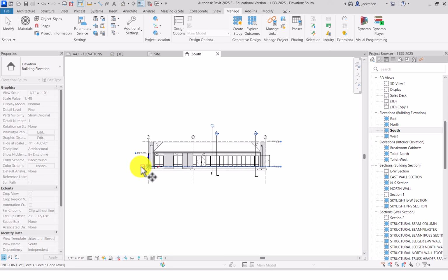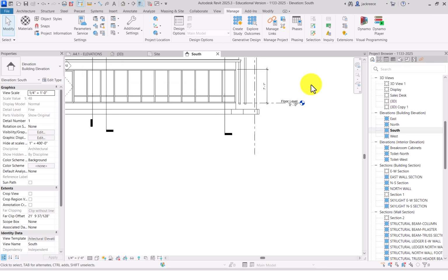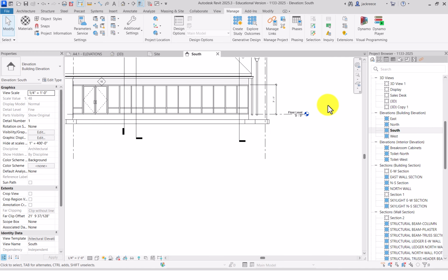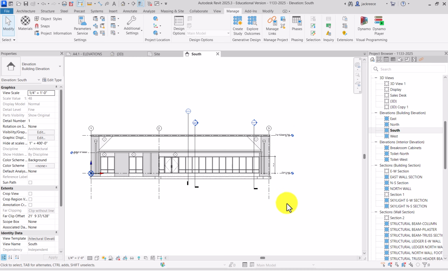And I'm just going to pick the end of my 0 level line and drag straight up until it's 844 feet. Okay. And now our architectural level elevations are still the same.